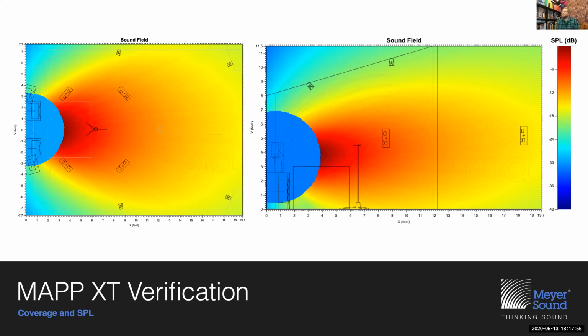It's kind of interesting how Dolby has defined their overhead channels for Atmos HE specifically, when they want a fairly regular, even spacing of those top surrounds above the primary listening spot. My first instinct when I looked at this room was to put that first front top surround immediately above the mixer and the back top surrounds farther back in the room. But having to play with Dolby standards, this is what the spec defines. So that's what we went with, so it would be accurately translated through all the different pieces of that signal chain.